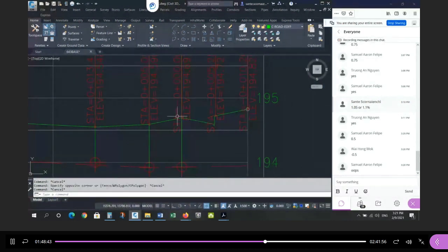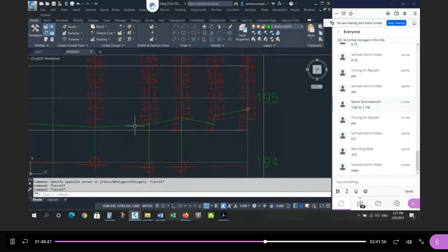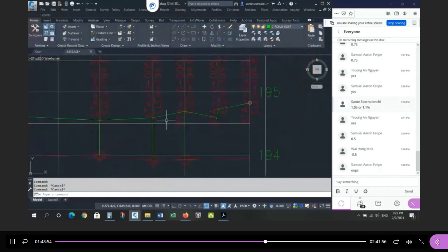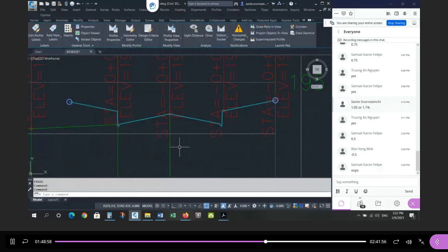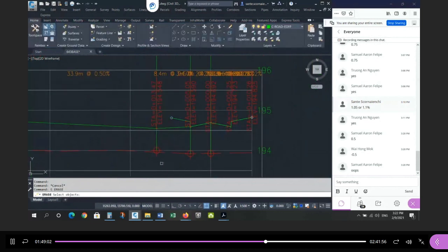This half is existing, this pavement is existing, and then from there we're actually doing our design, right? So our design really starts here, at the edge of asphalt. This is the first design point. Okay? If you want to keep it for reference for a while, you can, but I wouldn't show this in the design. It's only to get started. Okay, it's like when you project points, right? Now that these points are traced, you don't need them anymore.